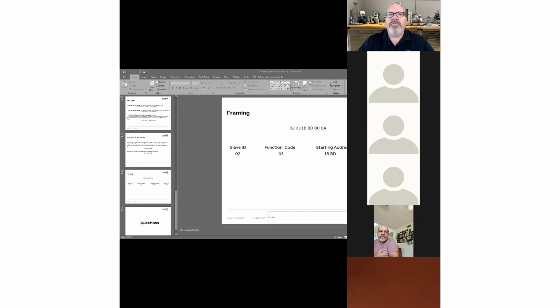This is a tool that's out there called Simply Modbus TCP. We'll go ahead and connect to a device. I have slave ID 1, and I'm going to read register 7101 for 10 registers. Now, there's not going to be an offset.